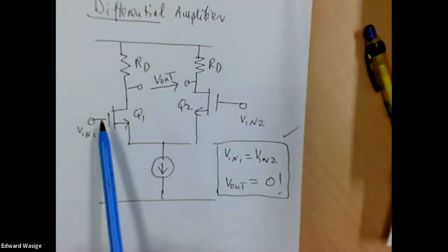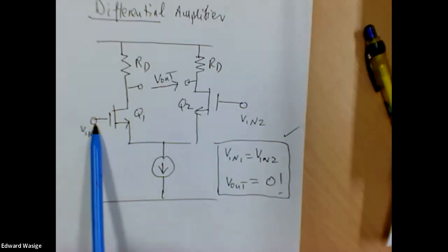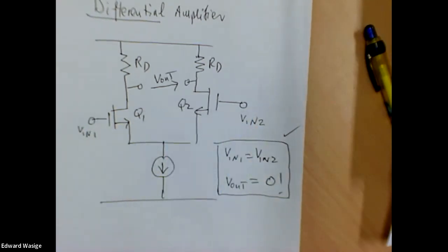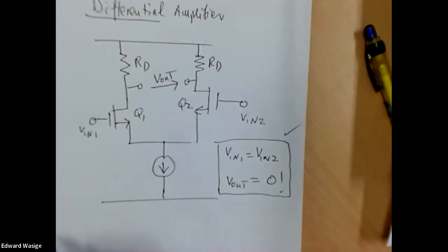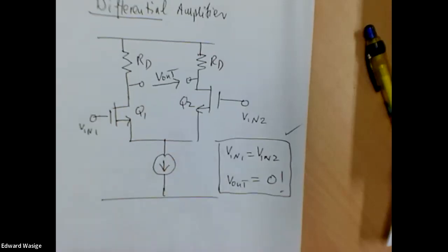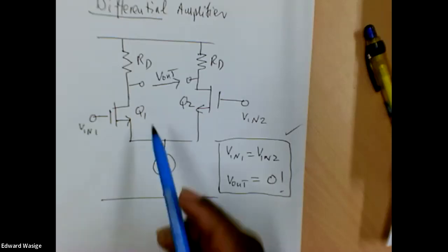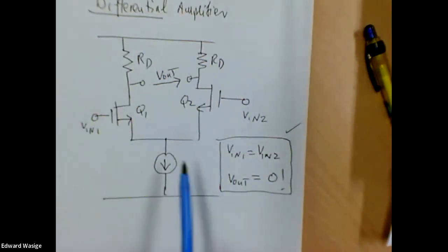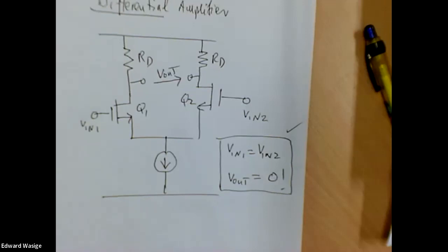But for the signals which we want to amplify, normally we can make this a reference terminal, and we put the signal that we want to amplify here. So the signal which we want to amplify is a differential signal, as it were, and it gives us an output. So I think that's enough introduction to the differential amplifier. It's plenty. You can read ahead of this. It can be a slightly abstract concept, but if you consider it as a common source amplifier, it's easy to look through, and we'll discuss this face to face on Wednesday.